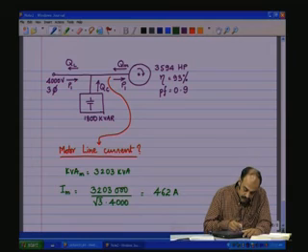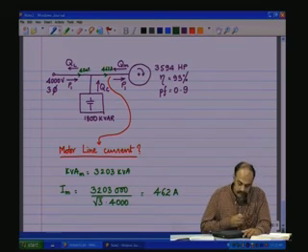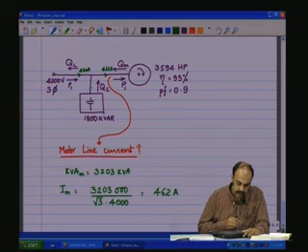So, you see that here the effective value is 462 amps, and what is here is 420 amps, reduced because of putting this kind of reactive compensation.